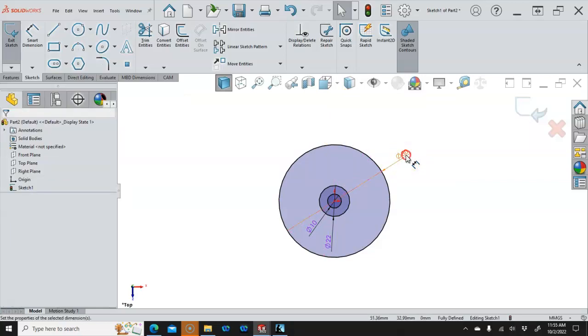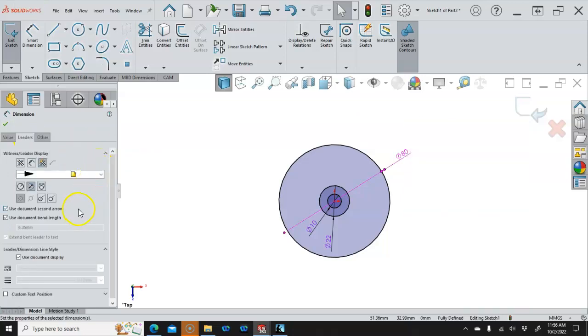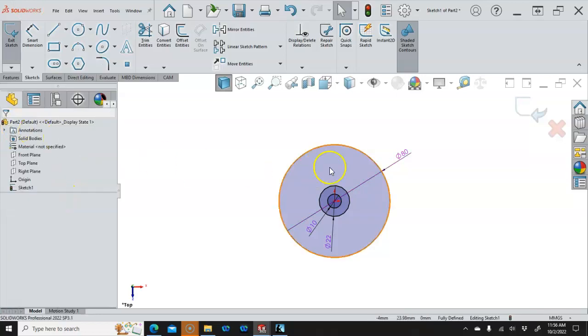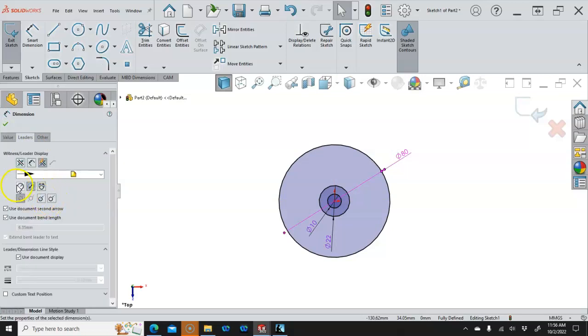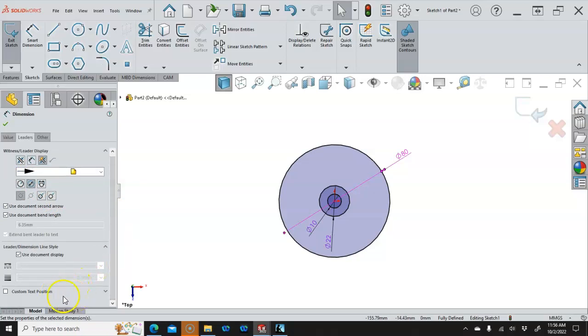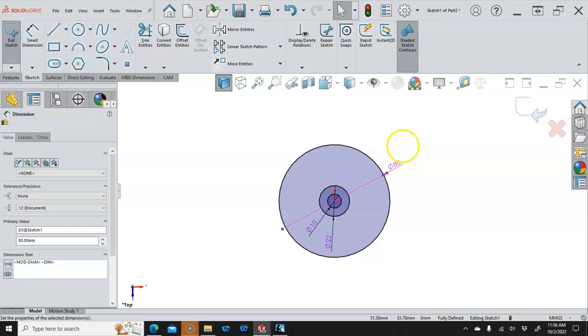So when you right click on any of these dimensions, if it's available for that, you're going to see the display as radius, diameter, linear, and then the auto, which usually we're not doing that close. So if I go back to the dimension, click on the dimension, go to the property manager, and then to leaders, that's where we're going to see the same radius, diameter, linear. And then also if it's a linear dimension with the circles, we'll see the max min conditions in that group as well. So just be aware and have an idea of where to find those.